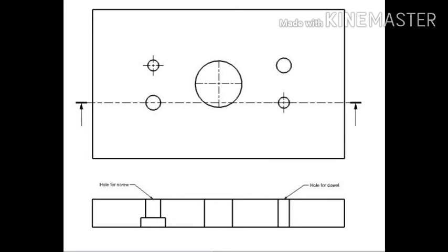The opening should not weaken the support of the die. During designing of the bottom plate, we have to see which precautions to take. The first point is that in the image you can see there is a rectangular opening. The opening should not weaken the support of the die. Second point is the blank should fall clear of the die without any obstruction.